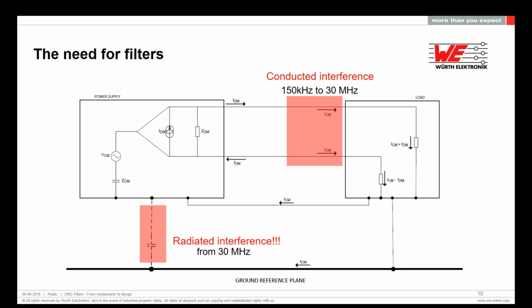And why is that? It is not like we expect to have other sources. We could have different sources for this noise, depending on whether we are radiating or conducting. But we could have exactly the same source of the noise, and depending on the frequency or the harmonics we have, it gets easier for our circuit to start radiating. So we will be designing some unintended antennas in our system, which will be emitting above these 30 megahertz. To have a good, efficient antenna below 30 megahertz, we need really long cables and traces, which is almost impossible to have in our circuit.